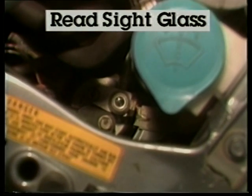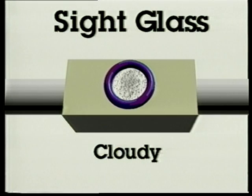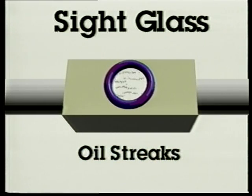The sight glass is often located in one of the lines or in the receiver dryer. To read a sight glass, simply note the flow under the small glass window. A cloudy sight glass might indicate that desiccant or drying agent is circulating through the system. The receiver dryer or accumulator would have to be serviced.